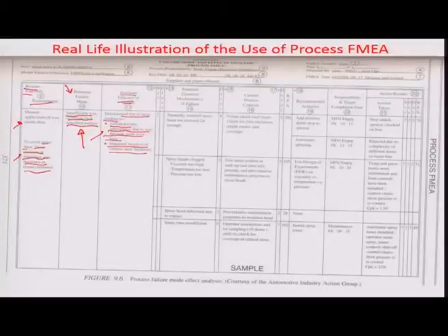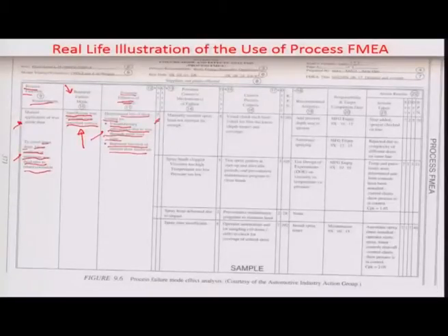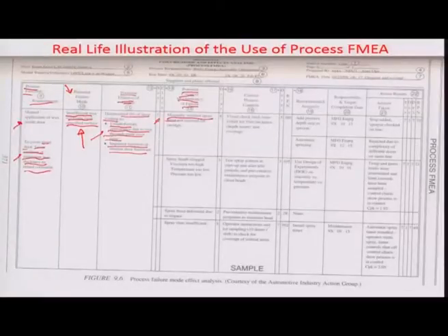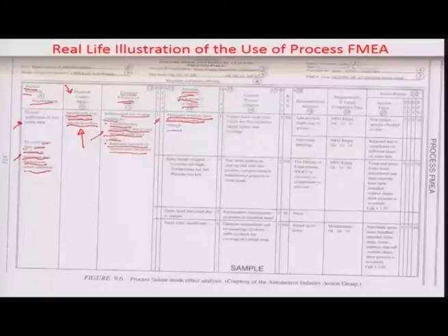So here, after looking at several different defects or a group of different failure modes, a quality engineer analyzes the severity of this particular defect, and he rates the severity of this defect to be 7 on a scale of 1 to 10 as compared to the other defects which are probably around. And then he tries to understand what are the potential causes why this failure is happening on a line by doing a line study. And what he finds out is that there are multiple causes which lead to such failures. One is that the manually inserted spray head, which is supposed to spray the wax on the door interior, is not inserted far enough so that it can go to the right depth where the wax needs to be sprayed.